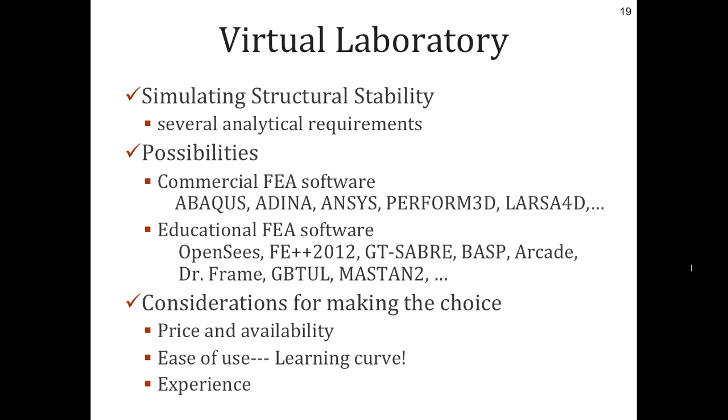So I just spoke to you about the analytical requirements to get there. Possibilities on the commercial finite element side, of course, the big three, Abaqus, ADINA, and ANSYS, can get you there. These are big programs and very sophisticated and probably a bit pricey for you unless your firm has them. Other ones, Perform 3D, LARSA 4D, Strand7, SAP2000. These are programs that are really starting to come forward with their nonlinear analysis capabilities and would allow you to sort of create this virtual laboratory.